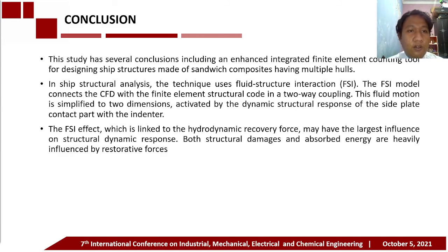In the last part, the conclusion, this study reached several conclusions, including an enhanced integrated finite element computing tool for designing ship structures made of sandwich composite having multiple hulls. In ship structure analysis, the FSI model connects CFD with a finite element structure code in two-way coupling. The fluid motion is simplified to two dimensions, activated by dynamic structural response and plate contact with the indenter. The FSI effect, which is linked by hydrodynamic restoring force, may have less influence on structural dynamic response.